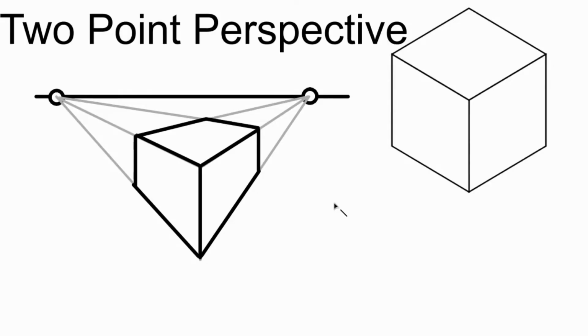Again, these are going to be a little funky. They're not going to look quite right, and that's perfectly fine. But these are how you do one and two point perspectives. Always, always, always start off with the horizon, then add in your vanishing points, and then either start off with your front view or start with your tallest height. Then from that point, you take your lines or endpoints back to the vanishing points, and then you start drawing out the views that are needed.